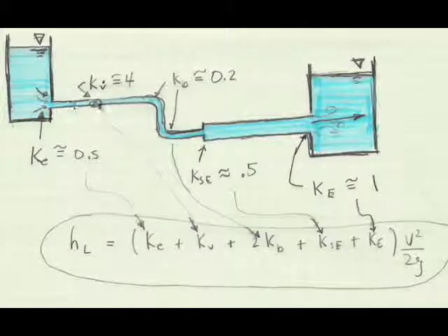Each component or transition has an associated minor loss coefficient or K values. K values are found from tables and charts in engineering references. Here I'm showing typical values. K values that are given in references are valid only for turbulent flow, which occurs when the Reynolds number is greater than 3,000. If you have laminar flow, you have to find K values from the literature.